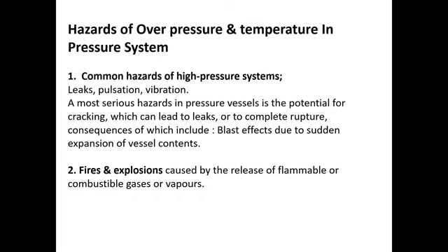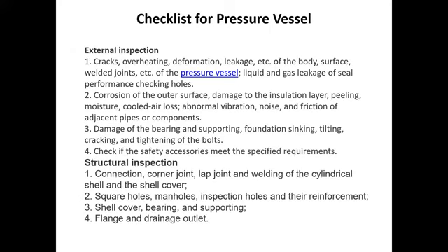What are the hazards of overpressure or over temperature in the pressure systems? There may be a leak, pulsation, vibrations. The most serious hazard in a pressure vessel is the potential for cracking, which can lead to a leak or to complete rupture, the consequences of which include blast effect due to sudden expansion of vessel contents, or there may be chances of fire and explosions. So if the pressure or the temperature is beyond the limit, then there may be chances of leakages, rupturing, blasting, fire and explosion.